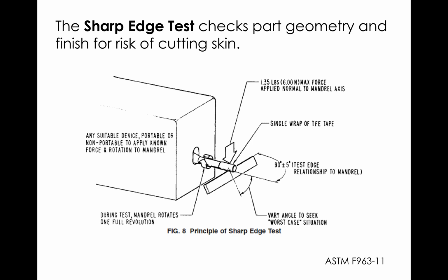Again, this is for parts as they are on your drawing, so your intact design. This same test needs to be rechecked if your parts would break apart during use and abuse testing. So if a kid drops it and your design breaks into two, you just need to check that those pieces don't then fail the sharp edge test.